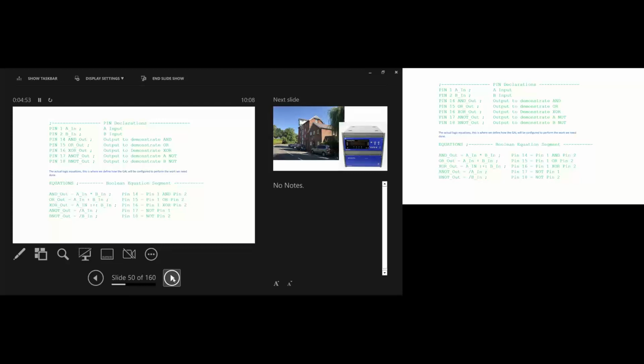One other comment: the 22V10, 10 outputs. Now we have 9-bit memory, multipliers, etc. in our FPGAs today. For video, we tend to use 10-bit wide buses, so you can't fully implement the devices. There's always leftover memory. It's just a comment for any FPGA manufacturers.